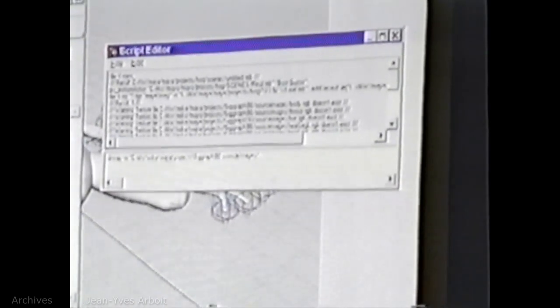The way you invoke dirmap is you do dirmap -m for map, and then you have to do it in double quotes. What I'm going to do is highlight the old path over here and copy it using the hotkey Control-C. I'm going to go in here and paste using Control-V. These slashes are reversed. You need to have them as forward slashes for it to work.